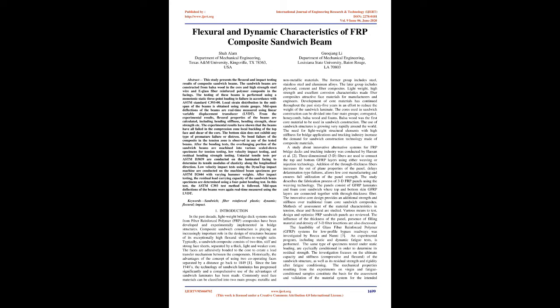composite in the facings. The testing of these beams is performed using a monotonic static 3-point loading to failure in accordance with ASTM standard C393-00. Local strain distribution in the midspan of the beams is obtained using strain gauges. Midspan deflections of the beams are real-time measured using linear variable displacement transducer, LVDT. From the experimental results, flexural properties of the beams are calculated, including bending stiffness, bending strength, shear strength, etc.